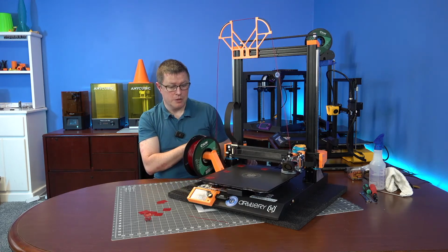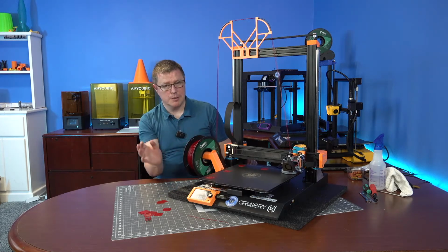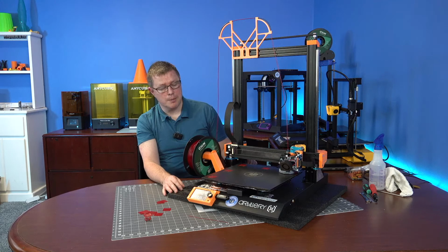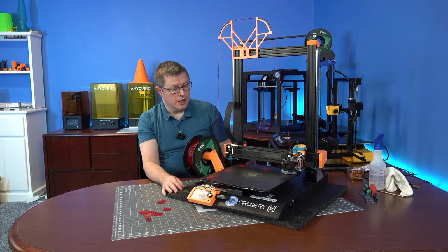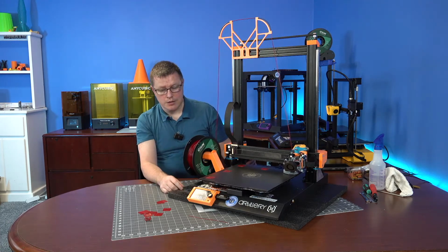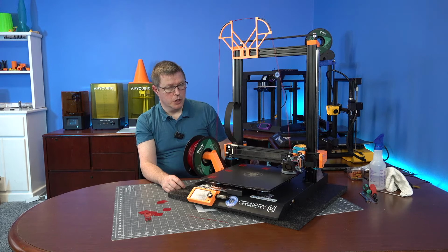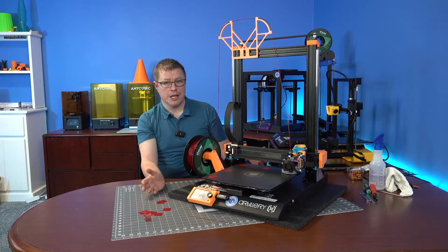The stepper drivers are probably getting kind of toasty right now, and when they do that, I would not depend on perfect looking prints. It will cause all sorts of weirdness. So this will probably turn out okay, but it's not going to be what I believe it should be. That side's all of a sudden in the wrong spot height-wise. The TMC 2100s I have for the Z-axis are getting mighty hot. If you print without the cover and without the fan, you'll have artifacting, and then when you put that back on, your prints will look perfect all of a sudden.